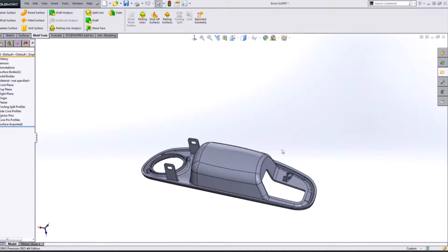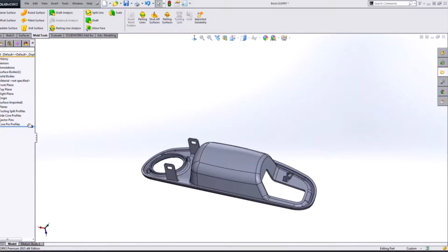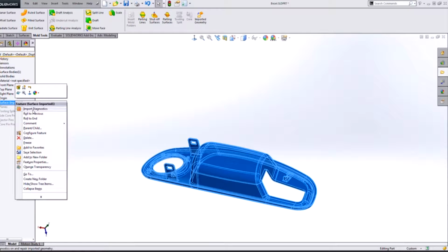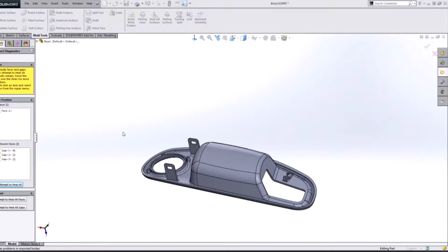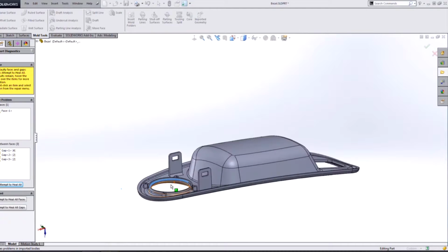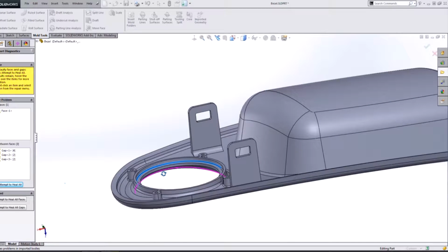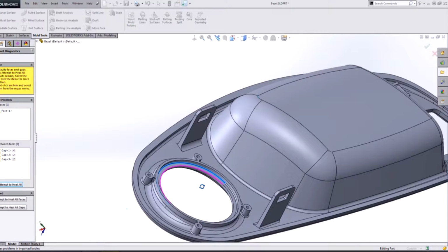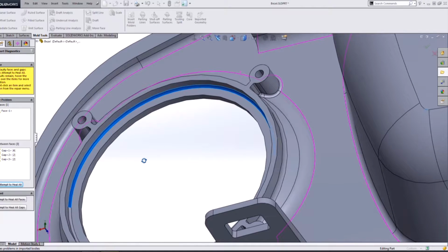Now recall, I turned that off, so what we're going to do now is reposition this in our feature tree and right-click on it to run those import diagnostics that would have started by default. When I do that, it detects that there is a faulty face, and it wasn't even one that I could see or tell was wrong when I first brought in the body. So you can see the benefit of this tool is finding things that you yourself won't catch with the naked eye when you first bring in a model.